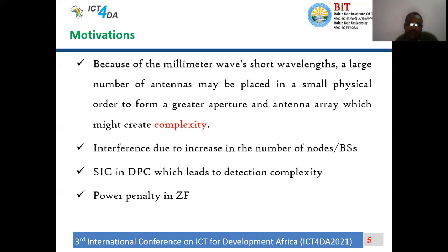That is still a problem of this precoder. And again, even though the zero forcing precoder, from the linear part, is known to suppress the interference coming from different directions, there is another cost related to this precoder. That's the additional power consumption for diagonalizing the elements of the matrix. And therefore, it creates some inefficiency in the system compared to dirty paper coding.